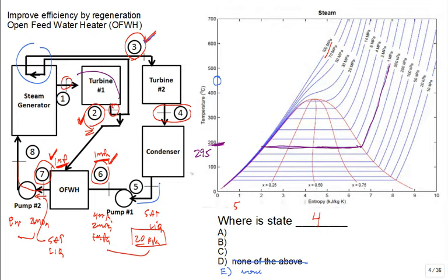True? So it came in at state right around here for 2. That was diverted, and some of it was diverted down to that feedwater heater. And then what happened? It was heating up the other fluid. But as it was transferring heat out of that stream, that fluid stream from state 2 to state 8, the temperature of the fluid didn't change from state 2 to state 8, did it? It just condensed. This is one of those oxymorons. It just doesn't make sense to students, right?